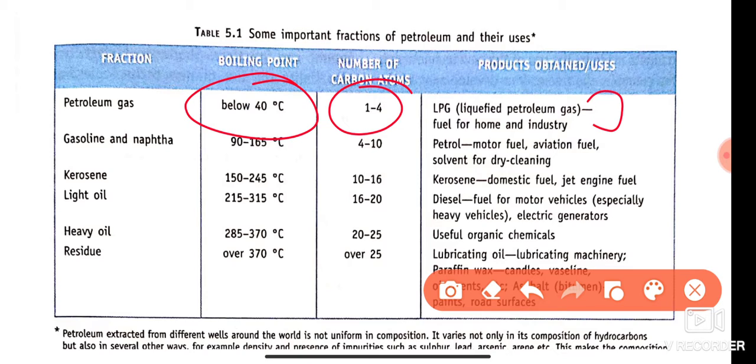Gasoline and naphtha, 90 to 165 degrees Celsius, 4 to 10 molecules; petrol, motor fuel, aviation fuel, and solvent for dry cleaning. Kerosene, 150 to 245, 10 to 16 molecules; domestic fuel, jet engine fuel. Light oil, 250 to 315 degrees Celsius, 16 to 20; diesel, fuel for motor vehicles, especially heavy vehicles, electric generators. Heavy oil, 285 to 370 degrees Celsius boiling point, 20 to 25 molecules; useful organic chemicals.